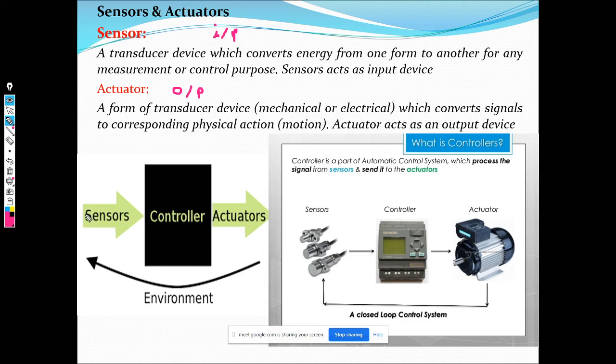So the embedded system goes like this. You get the data from the environment through the sensors, and then the controller controls it, and then your actuators will respond to it, and then the feedback goes. For example, this could be your temperature. You take the current temperature and compare it with what you want to set it to. If the temperature is more, then you trigger the control for the AC. Your actuator will trigger a relay, or control the motor of a fan to control the airflow.